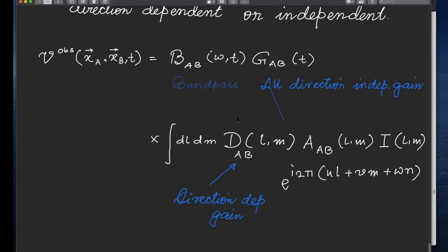You can think of it this way: you have done the calibration, then your gain is 1 plus delta, and your phase is e to the i phi, where phi is very small, because you assume that you have done the calibration to some accuracy, right? So what you have not taken care of is the signal times the residual gain, and because it's residual, it's much less than 1. You can get it down to some level, but not much below, but it will always be less than your signal, no problem.